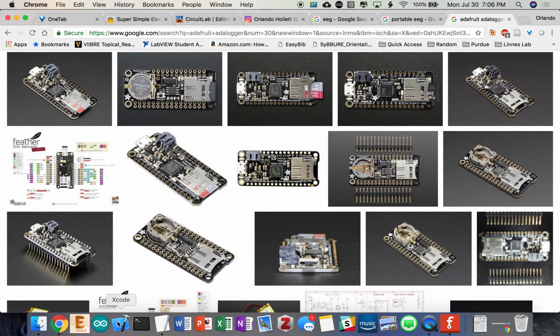A microcontroller is a lot more built for that versus something like a Raspberry Pi, which is an operating system, does not do things like keep time very well because it's not really made for that. So for the microcontroller, I could say, I want you to sample this signal or do this process once every 10 microseconds. I can't do that very easily on a Raspberry Pi.